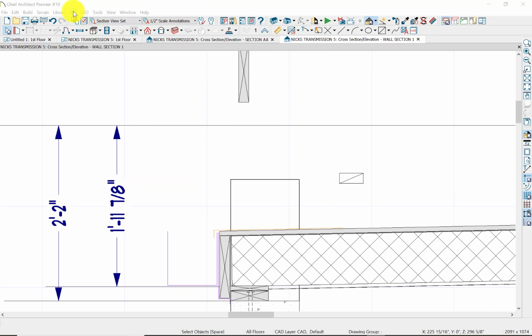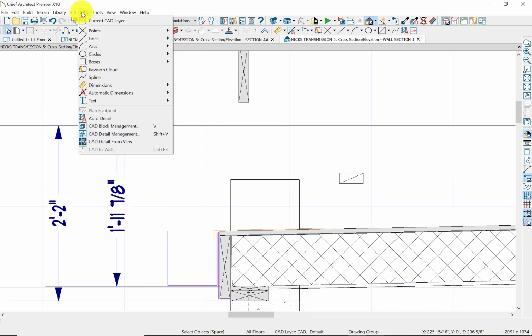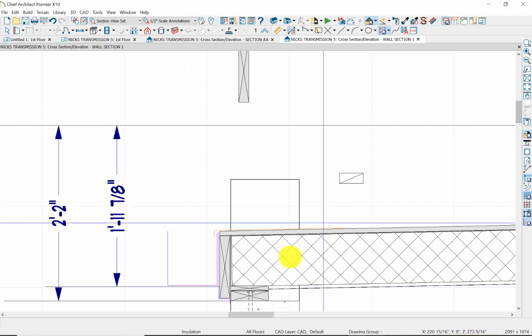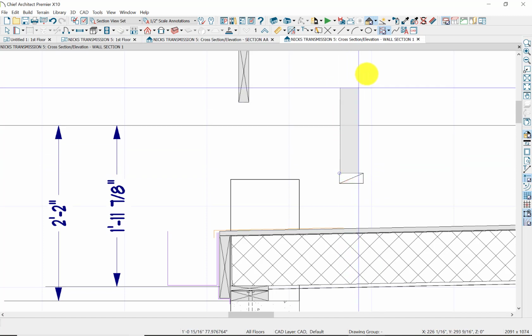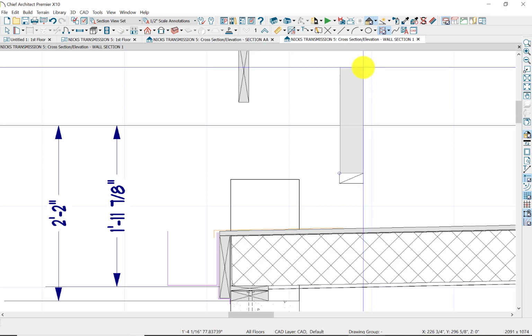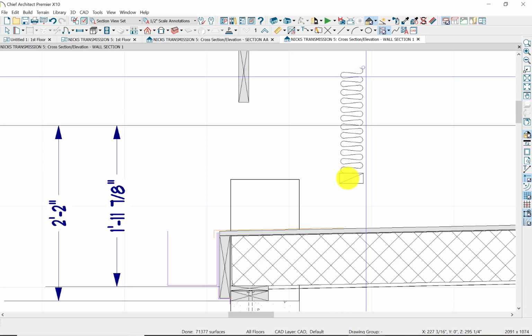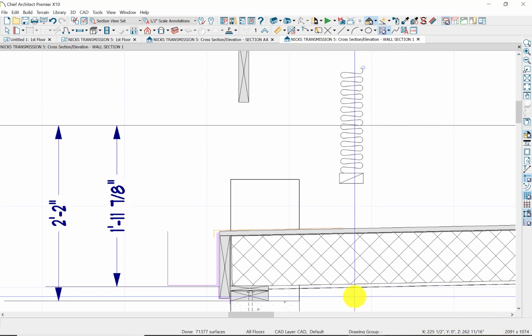All right, now I'll show you a cool way to pop in insulation whenever you need it. Boxes, insulation, but first, let's just click insulation. And let's say we want to insulate the stud cavity here. So we just go there. Let's say this is studs. And as you draw, it'll draw the insulation in there. So that's a pretty nifty little tool.